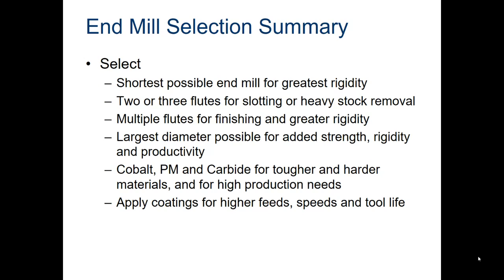All right, so a couple of things you want to be thinking about when you start making a selection as to what you're going to use to cut. When you're choosing which tools you want to use, we're going to look at the most important ones here. First off, you always want to make your end mill as short as possible. And again, it's just about rigidity. You don't want vibration.